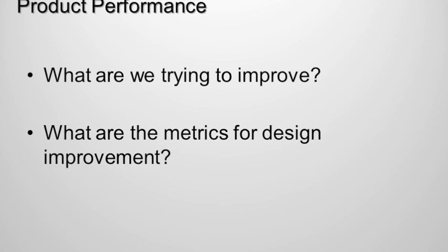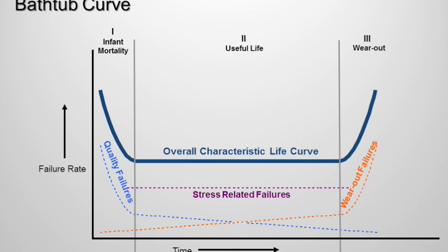So where do we start? How do we create a metric? What do we frame it with? Well, one common way that I like to frame it is within the foundation of the bathtub curve. And for those that aren't familiar with the bathtub curve, the bathtub curve is created to demonstrate what is a very common progression of field reliability with a group of products.